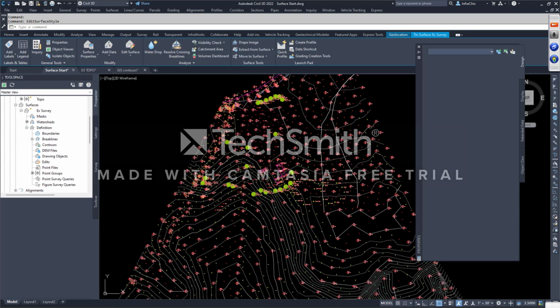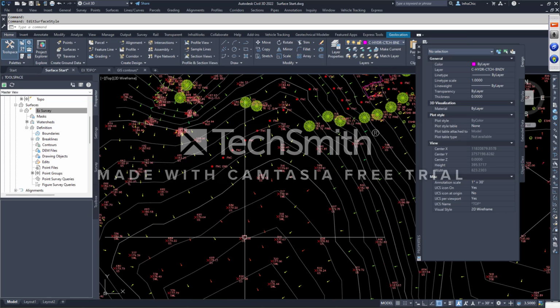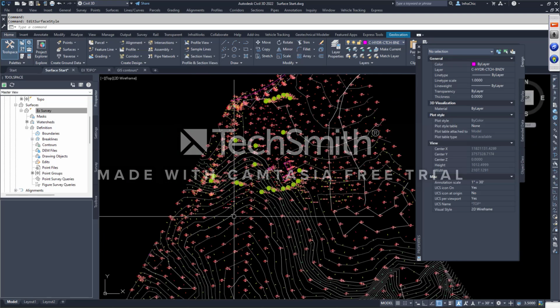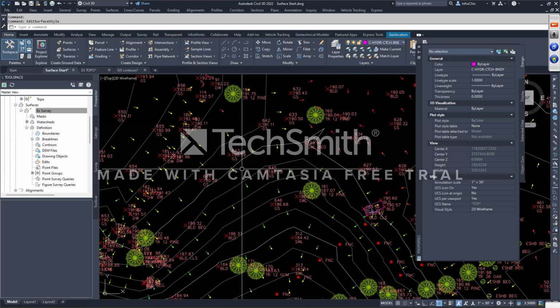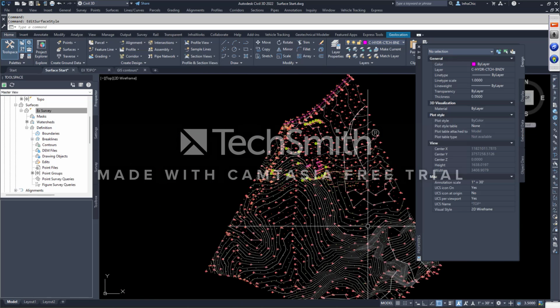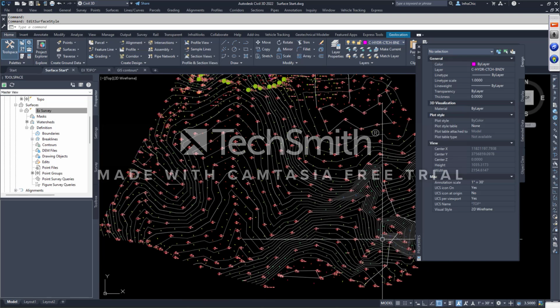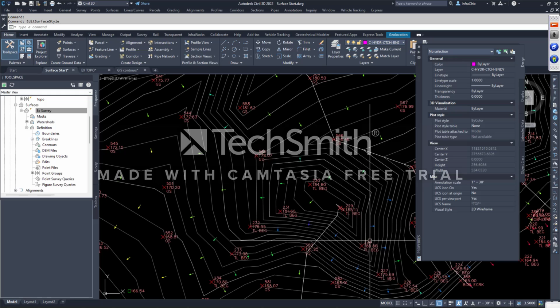And here we have a ton of different slope arrows. So red was the shallow, and it kind of went up in orange and green. So green is kind of steeper. Yellow was like 2%. 1 to 0 was red. So it's pretty flat in most areas. I'm not seeing a ton of purple. Ooh, there's some steep guys right there, right? 25, 30% slopes in blue.